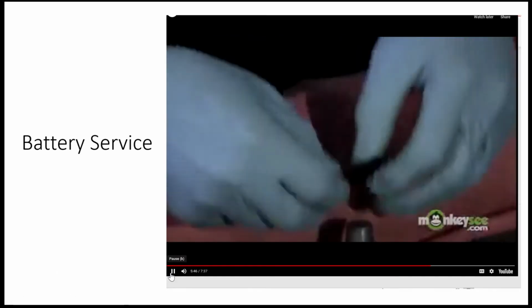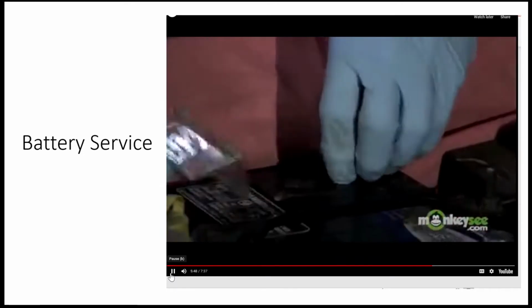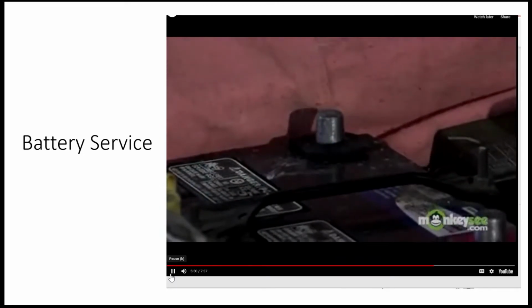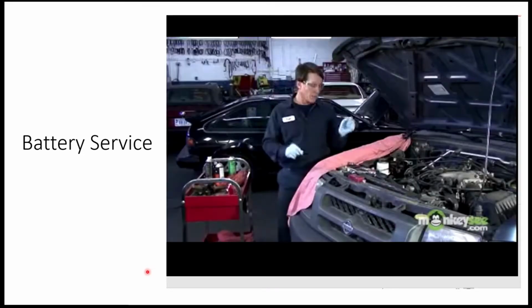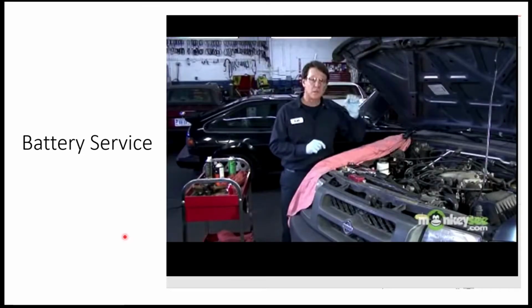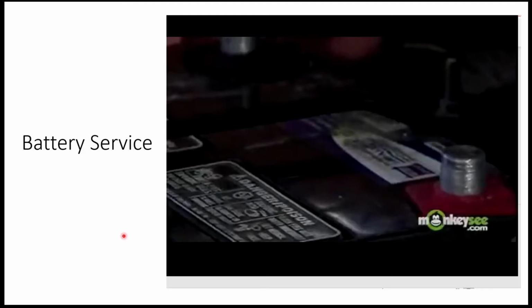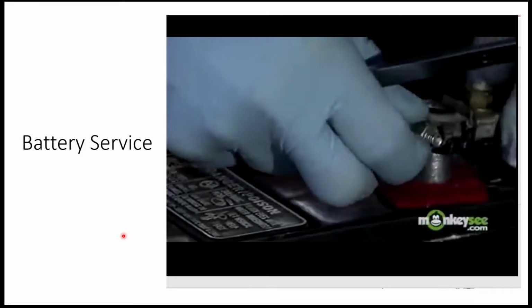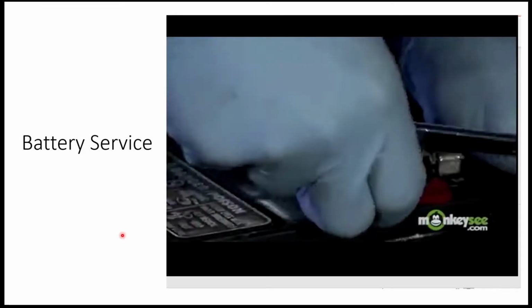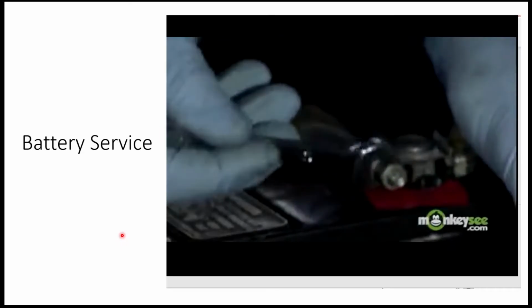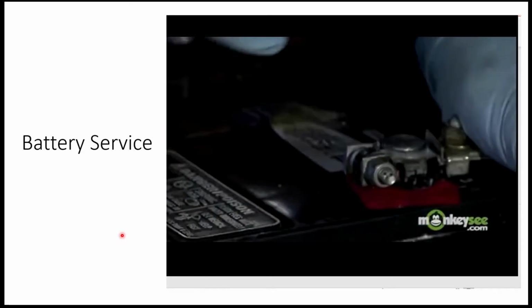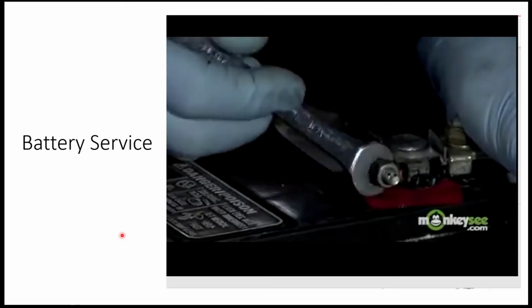And a black terminal pad on the negative post. Again, remember, negative terminal is the last terminal connected. Now I'm going to install the positive cable. I'm going to make sure that we push it down so that it's oriented correctly, all the way down to the top of the battery post, slightly protruding through the terminal end.